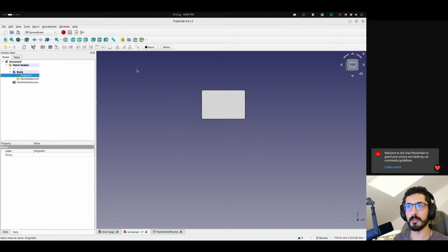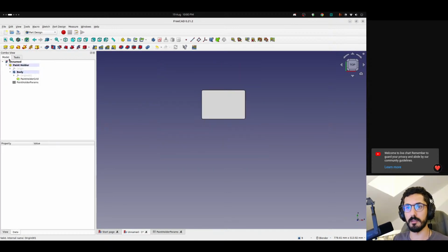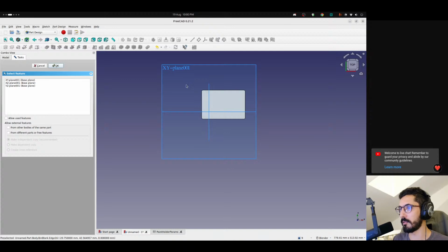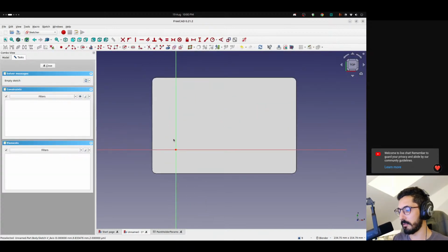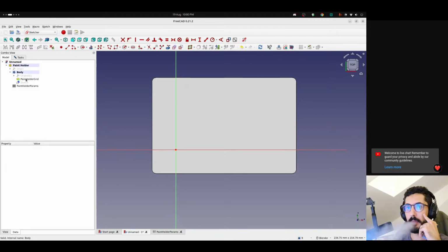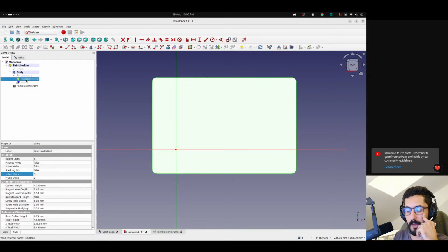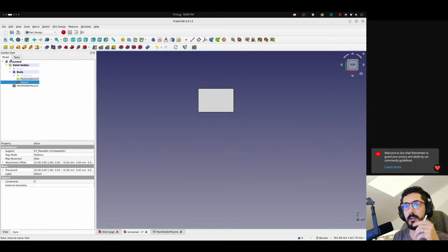So like this, go to Part Design. The body is already active. Let's create a sketch on the XY plane. And we want to know where this line is, right? And it was probably a good idea to create a datum plane, but give me a second. We will do that. Or we can move the body. Yeah, let's close the sketch.